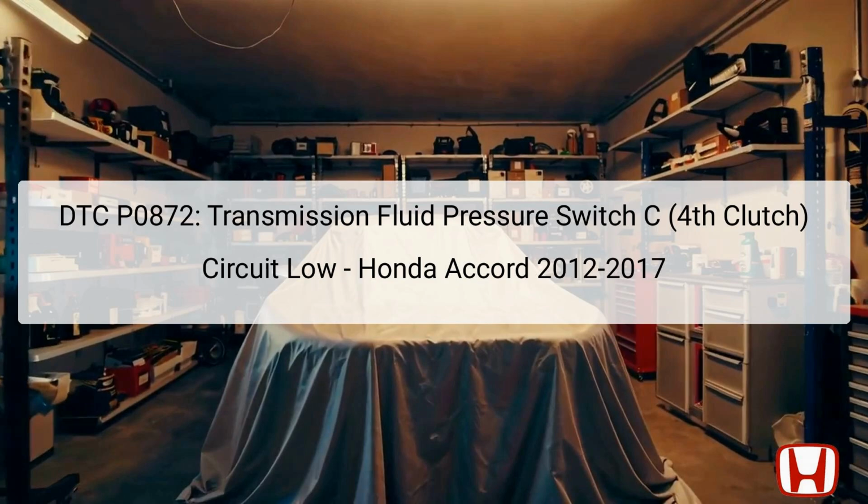The transmission fluid pressure switch is critical as it detects whether hydraulic pressure is being supplied to the fourth clutch. When operational, the switch sends a signal to the Powertrain Control Module, PCM, to manage fluid pressure and reduce gear change shock, specifically when shifting from third to fourth gear. If the switch indicates an erroneous state while the vehicle is not in fourth gear, the PCM identifies this as a potential failure, triggering the DTC and warning indicators. Diagnosing this issue involves thorough examination of the switch and related circuits to ensure proper functionality.